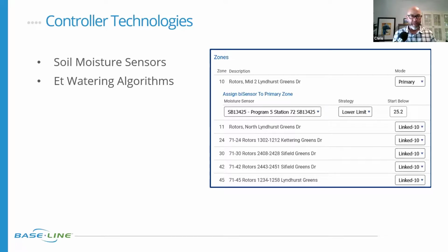using the new precip sensor technology to manage water efficiently? This is really where we get to combine two technologies, a tipping rain bucket technology and a soil moisture sensing technology, into this precip sensor and precipitation management, if you will. Step number one, pause when it's raining. Don't stop when it's raining, but pause, which visually looks the same. Let's just turn the irrigation system off, but do it temporarily by pausing.